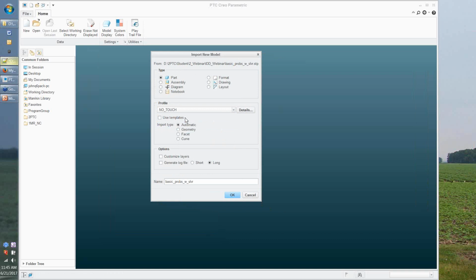This adds to the problems that occur in the import of the file. If I model the originating file at, for just talking purposes, say 1,000th English unit accuracy, and on my own part template I was half of that in accuracy, at 5/10 English unit accuracy, I would in fact be trying to import the part to a far greater mathematical condition than what it was created at.